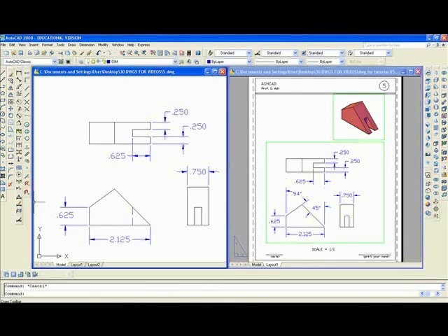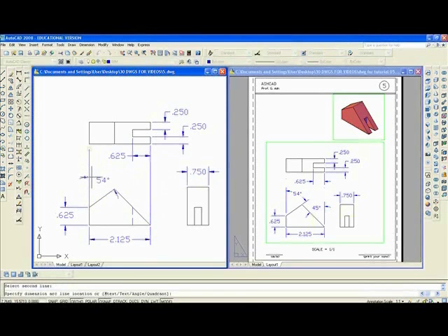Now then, in order for you to create an angular dimension, you need two lines. So I'm going to draw a line with the O-Snap on, Ortho on, from this point up here like that. I'll also draw another line, hit the spacebar again, up here like this. And now I'll go to angular dimension, which is here. And you do this counterclockwise. Pick the two lines till you get it the way you want it, like that.